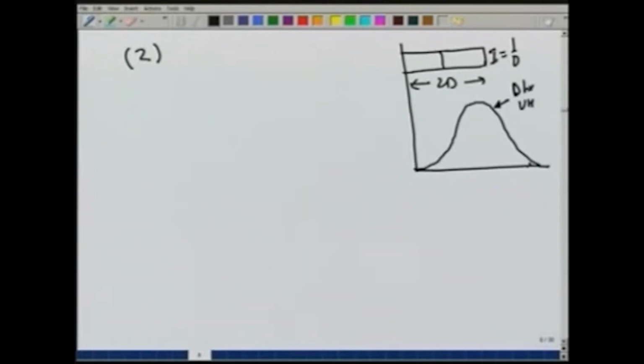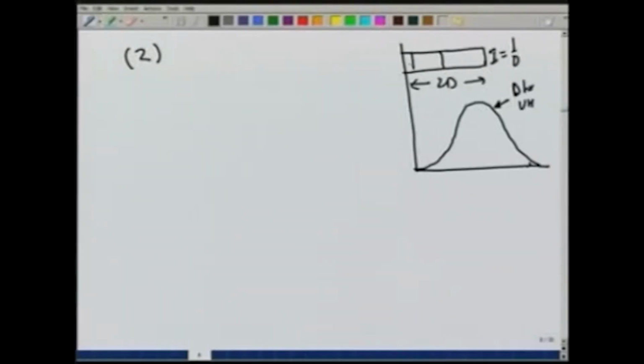Here we would use again the concept of time invariance and linearity. So, if we use the concept of time invariance and linearity, it leads us to the method of superposition. So, we say that if there are two different storm events occurring, then we can add the runoff due to each single event and get the total runoff. So, if this is the UH, D hour UH for the first storm, it would work fine, but for the